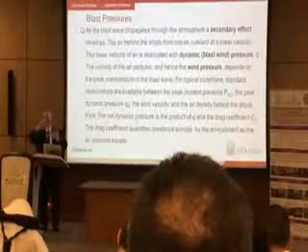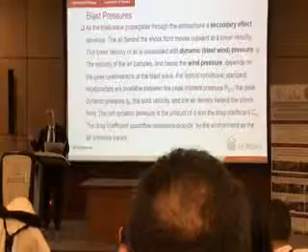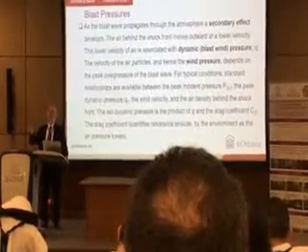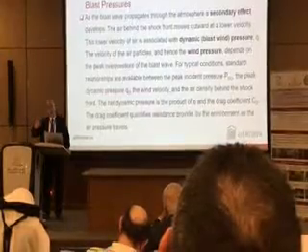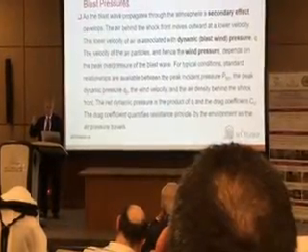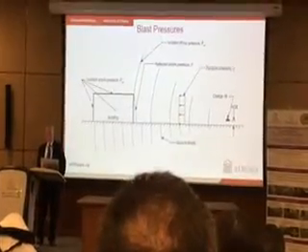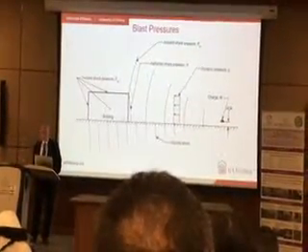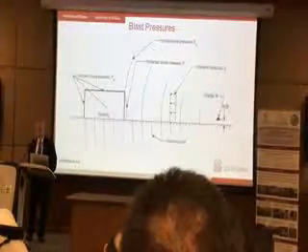building. As it's coming down, now the second wave starts coming. This is called dynamic pressure, and it is usually slower and it takes more time to reach the building, but the combination of that gives you the shape that you have seen. These schematics represent that. First the shock wave comes, it reflects, and then dynamic pressure comes.